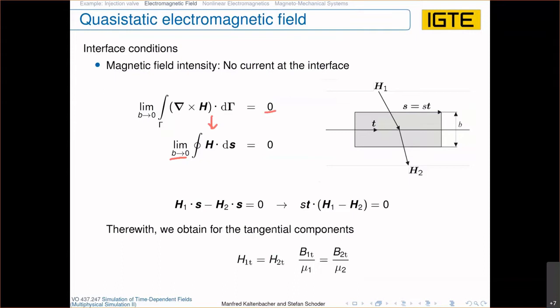So we already see that the magnetic field is a quite complex physical field. You will not have really smooth solutions in this sense, because you will have interfaces, especially between iron, for example, and air, where you have jumping physical quantities concerning B and H. So this needs special care when we turn the partial differential equation into the weak form and perform a discretization with finite elements.